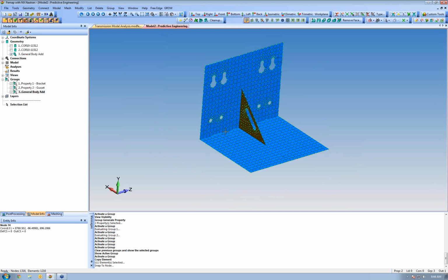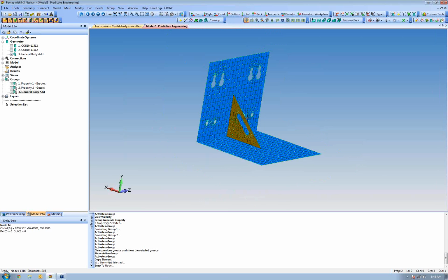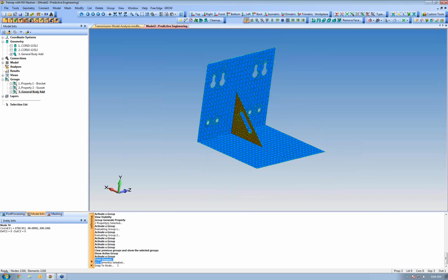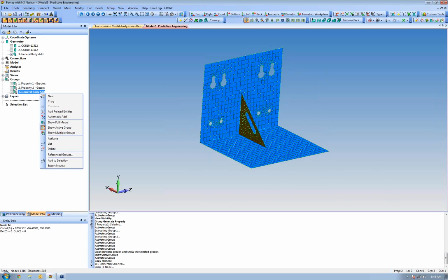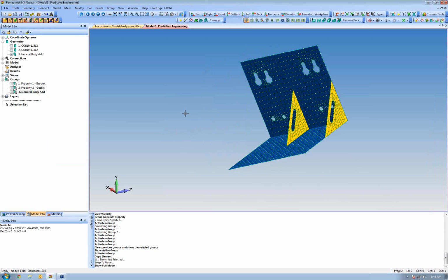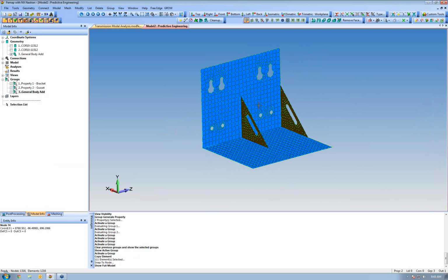Okay, so I copied the element, and all of those elements have been gusset, and they're nowhere to be seen. You can see in the dialog here, copy element, you've got those elements copied. Our element count has gone up, but where are they? We show the full model. They were successfully copied, but we were viewing the active group, and they weren't automatically added to the active group.